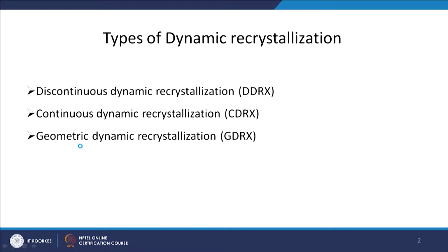Actually, most of the studies and the modeling, numerical or analytical, is done on the discontinuous dynamic recrystallization. Initially that was the most important microstructural change which people saw and understood. The continuous dynamic recrystallization is the later addition, and we will try to understand why it has now become important.